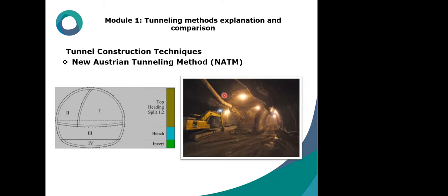Soil mass around the lining of the tunnel contributes to load bearing and helps to withstand the loads. So total overburden loads won't be sustained by the tunnel lining due to the arching. This phenomenon will be extensively discussed in the relevant section during the diploma. Also, this method is economical and flexible for different kinds of situations.